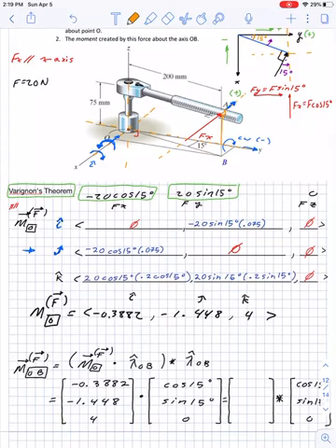Now that is going to be our moment arm. That moment arm is the same thing as this distance right here. This distance is in millimeters, so I converted it into meters, which is 0.075. And that's how we get a negative, because it's clockwise: 20 cosine 15, which is the magnitude of f of x, multiplied by the moment arm, which is simply z.